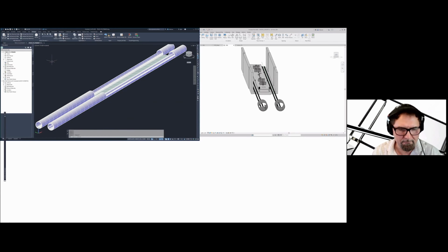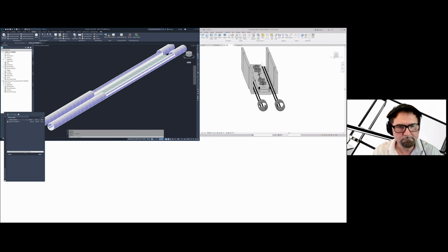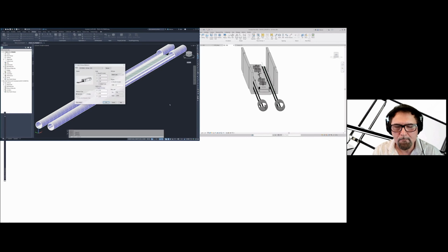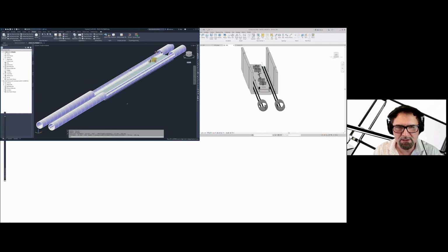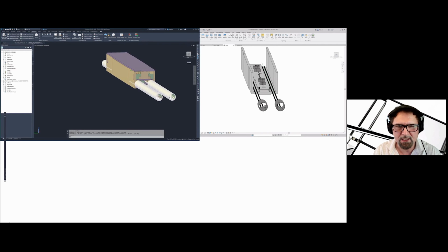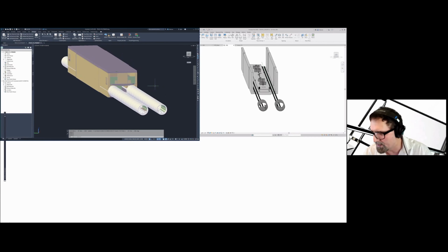So first of all, we can attach that Revit model. That's the one. Without any specifications, this is just using the same shared coordinates. And I didn't go much into the shared coordinates concept. You can see here all of the detail in the station as I'm moving it inside. You could use your standard project point with setting up shared coordinates and get that level of synchronization.